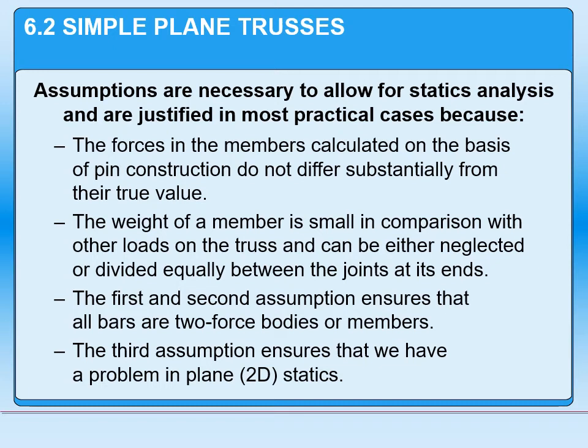Lastly, the third assumption is that we have a planar structure, that it's a 2D structure. And as you could see from the earlier photographs, and hopefully from your own experience with truss structures, they are relatively flat. That's how they're manufactured. And in fact, trusses are far more stable when they're flat. So most often, that's how they're designed. If we do get away from these types of structures, we have ways of dealing with 3D analysis. We'll talk about that next unit, but it does get significantly more complicated.